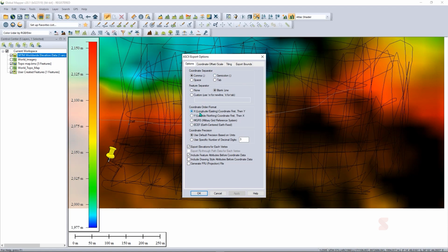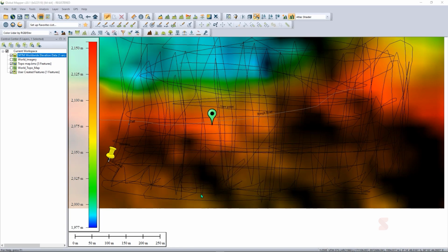So under this, we can change what we want. So for here, we basically have which point we'll start. Do you want to start with the easting? So for our case, we are using the PENZ. If you remember, the points, easting, northing, elevation, and description. So this is the correct setting. All these others, you can just leave them as is so that you do not alter and tamper your data. So I'll click on OK.